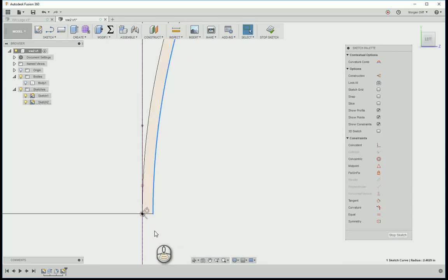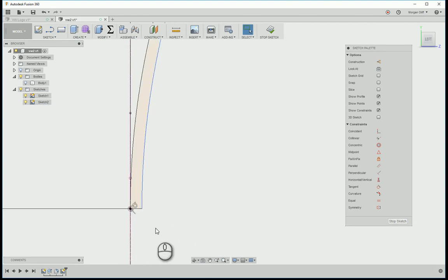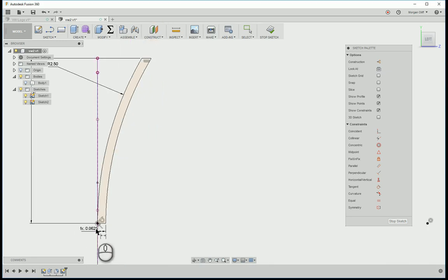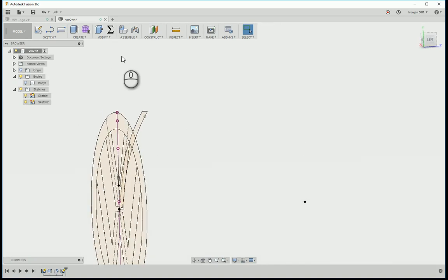So we just need to pick a thickness, and this is a good case where we would press D for dimension here. Grab this bottom area here and say that it is the same as we did our flat extrude, D1 times 0.025, so 2.5% of D1. So yeah, 1/16 of an inch in this case. Stop sketch.